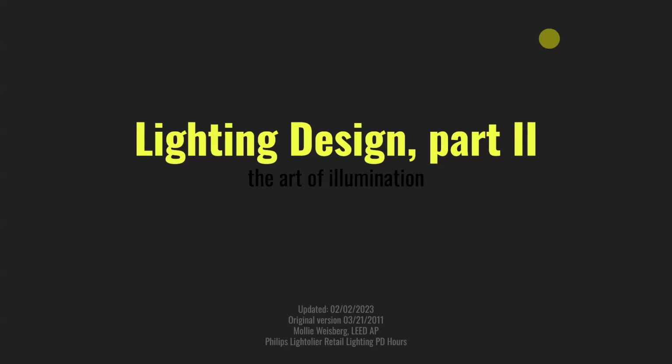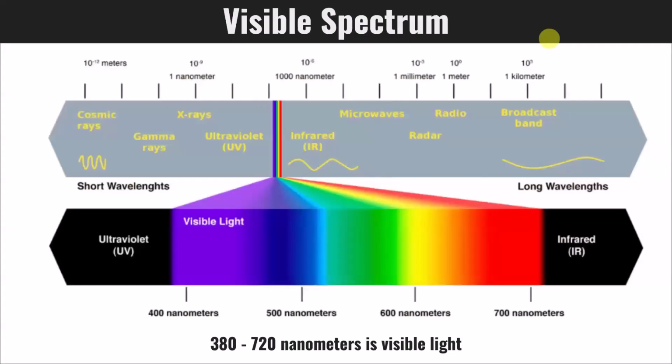We can backtrack if we need to, but we are starting now looking at CRI, the color rendering index. So basically, at color rendering index, you have what the light is going to provide you, right? That's the main tool we have for seeing color is light. Correlated color temperature is related to color rendering, basically to do with what light is painting the space. All right, so how cool or warm that white light is. And then foot candles is related to the brightness. Okay, what actually hits and bounces off surfaces. That's the main reading that we use.